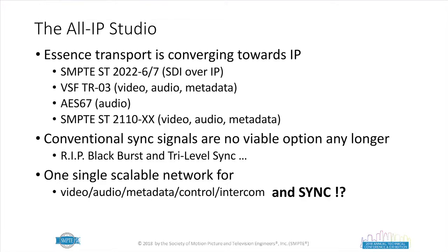We had, as previously mentioned by Paul, systems which were based around Blackburst, tri-level sync, or other means to carry that type of information. We came up with this model where we want a converged network to have only one cable for all the different parts of the essence and the system, including control, intercom, and whatever else may be in the mix. So why not add sync onto this too? There's obviously the basic precepts of what we're trying to build here.